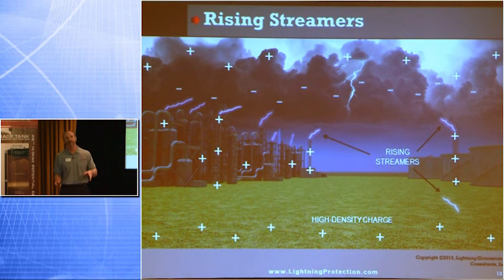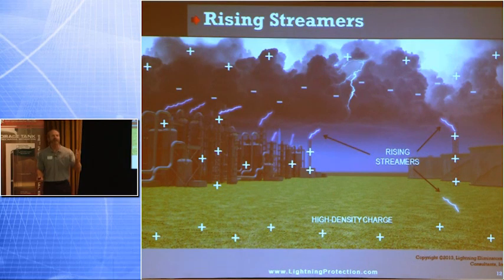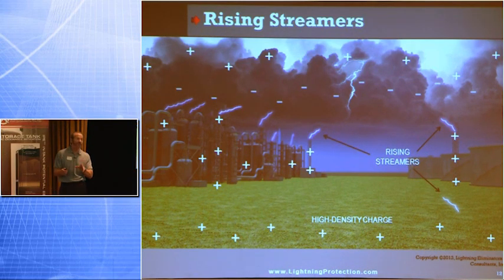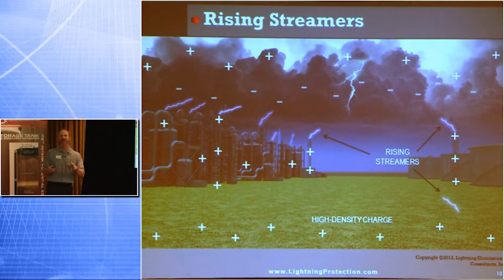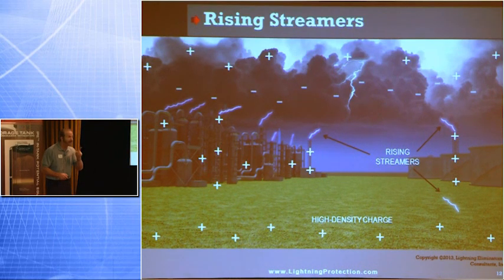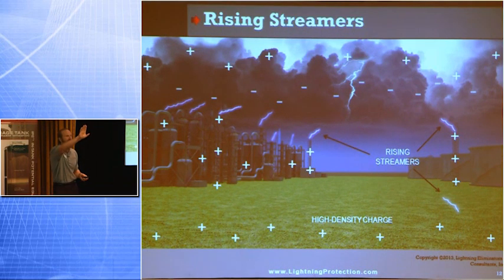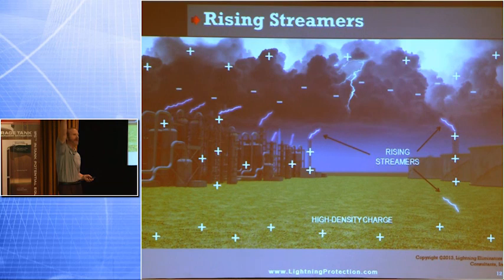On occasion we get asked a question in an engineering presentation, somebody will ask me, hey, I heard lightning comes from the ground up. Well, the answer is yes, you can get ground generated leaders and lightning. In fact, to get upward generated lightning, though, you have to be about 100 meters in elevation. In other words, it's extremely rare and probably not going to happen to get an upward generated lightning leader, not a streamer, from the Earth, unless you're like a tower. This tower might be 100 meters tall, maybe it could generate it. You might be sitting on the horizon and see that tower in the distance and generate a leader going up from the Earth. Very rare, possible, but it typically has to be over 100 meters tall, 300 feet tall.